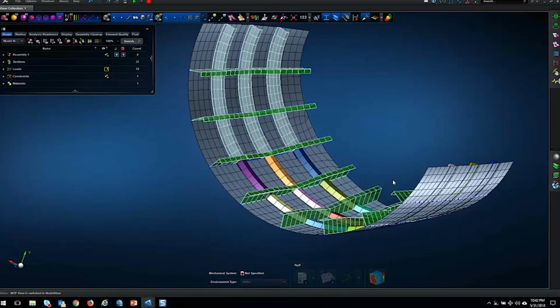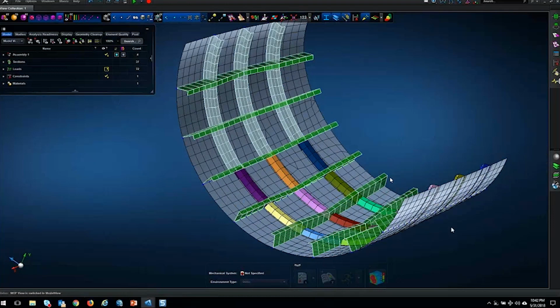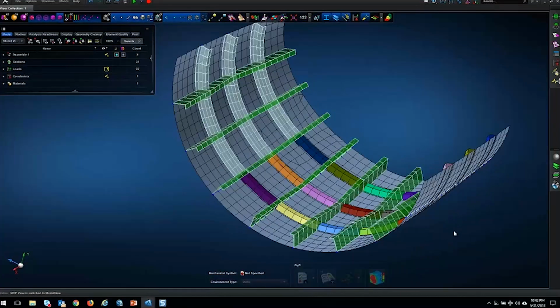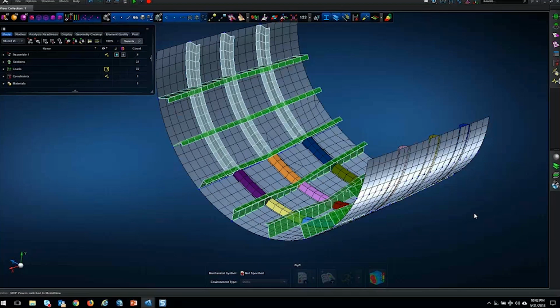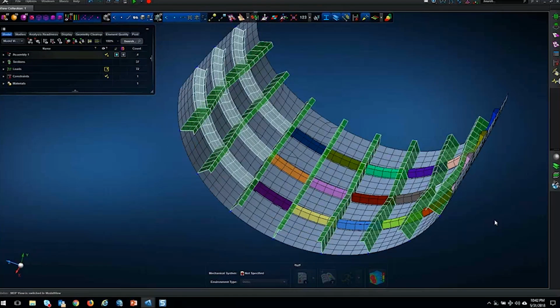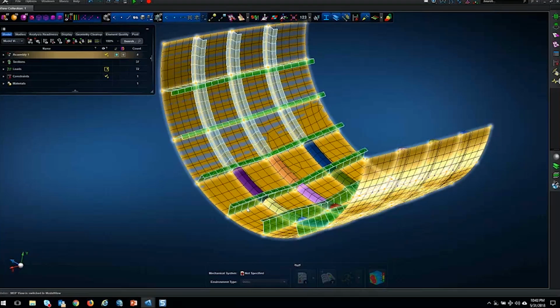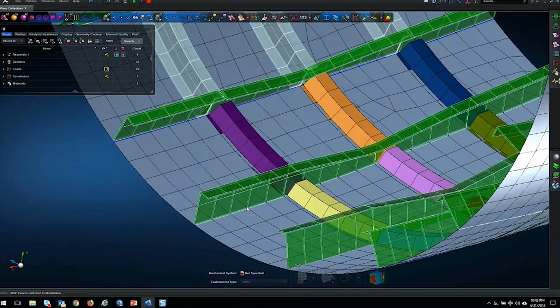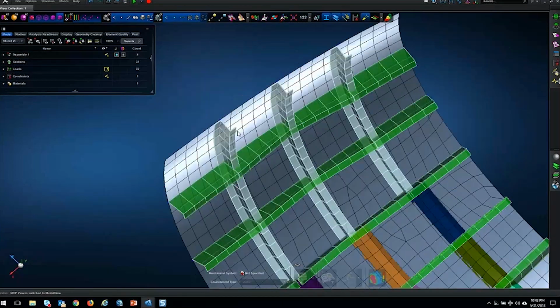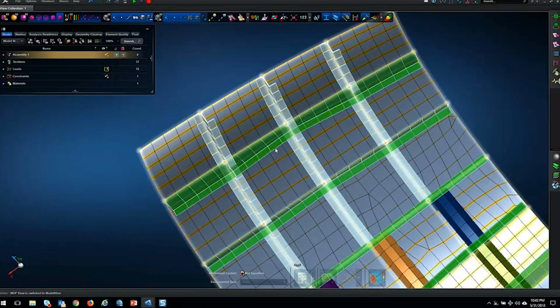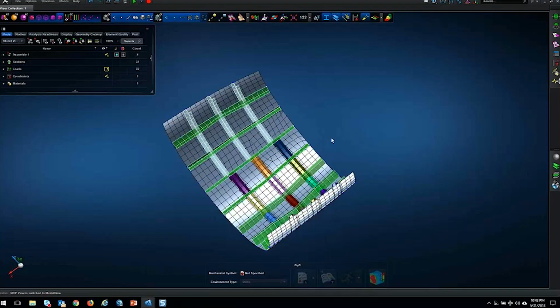It's the same model I rendered with all these beams, as you can see here, and there are the 1D profile shapes that I created for some of these curves, and there are some tapered beams of L section that I created, and also for some curves I did create a Z shape, assigned to this one.